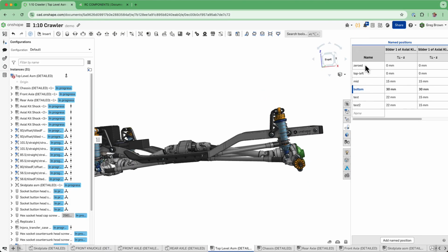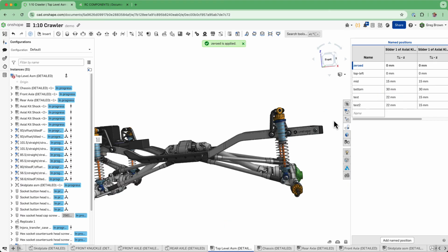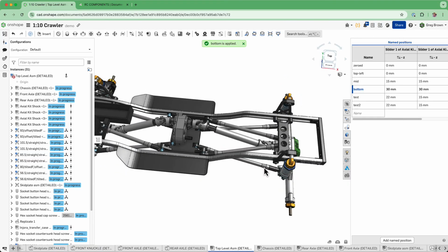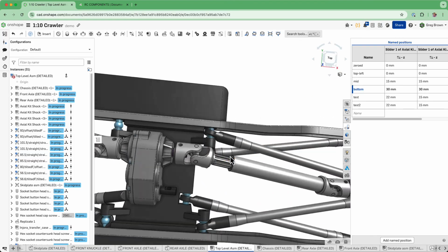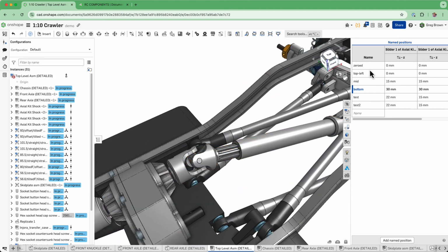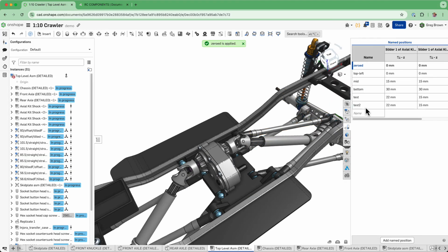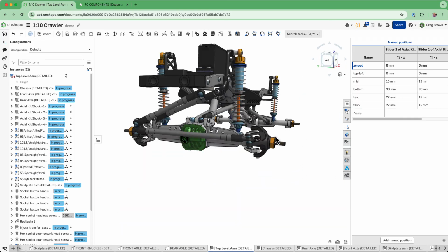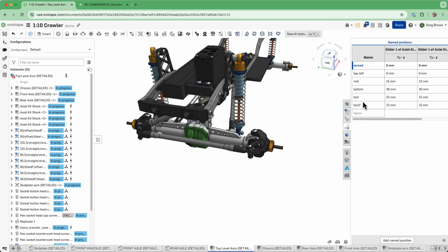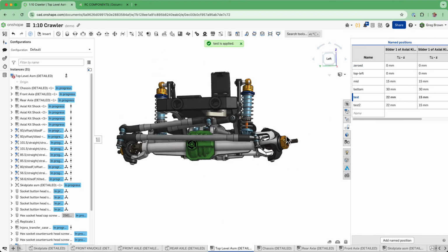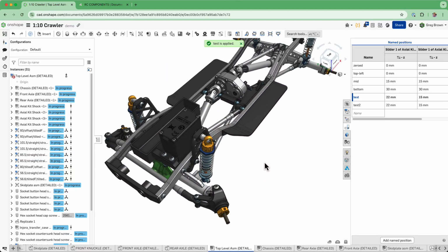You can see here, if I top out the suspension here versus bottoming out the suspension here, I can then come in and again assess some of the potential bindings. I'm looking here at the drive shafts as well. So let's go back down to the bottom. You don't want these to be binding. Of course, they're not. We can also test some steering extremes. I think there's one here. Yeah, these two down here test the extremities of the steering at the top of their travel.